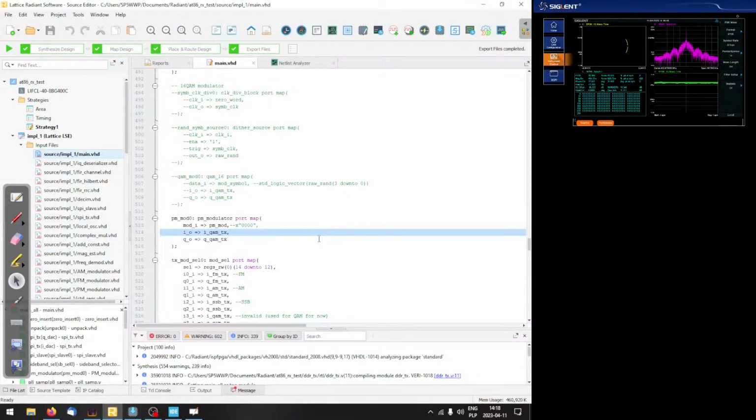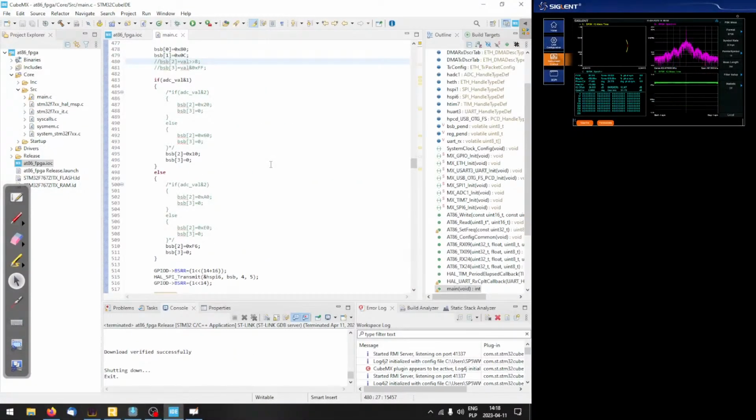So let's take a look again at the spectrum. We are back with the settings that we had a few days ago. The problem was that the spectrum didn't actually look like PSK. It resembles the PSK spectrum, but not quite. One of the things that's not normal is the DC peak at the center. We actually don't want that.